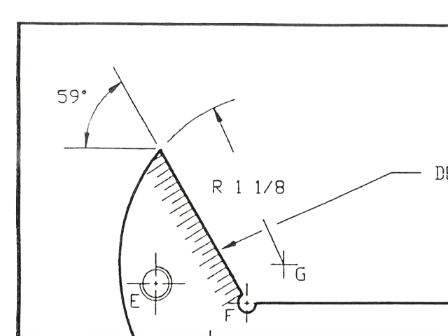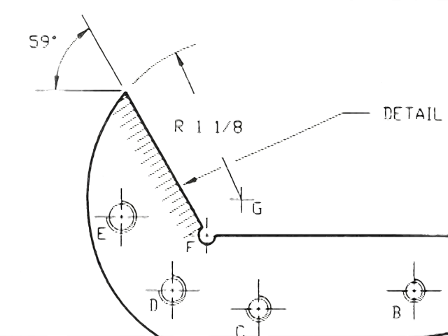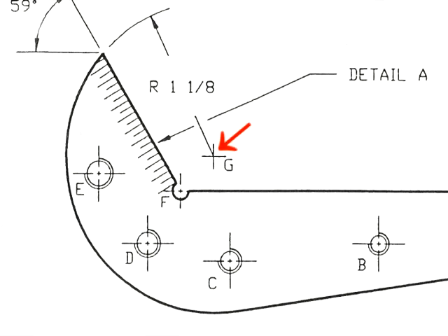Sometimes they seem to extend from nothing, as is the case with this extension line here, which is actually the offset extension of the project's horizontal plane. Sometimes they're curved, as is the case with this extension of the 1 1/8 of an inch arc. And this center spot here is actually another way of showing a type of extension line.